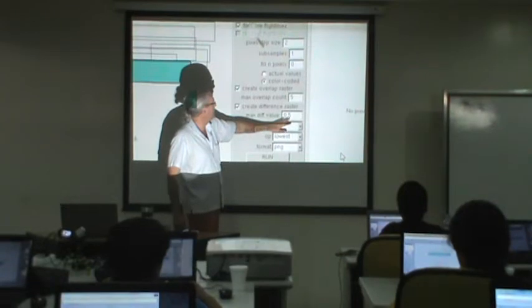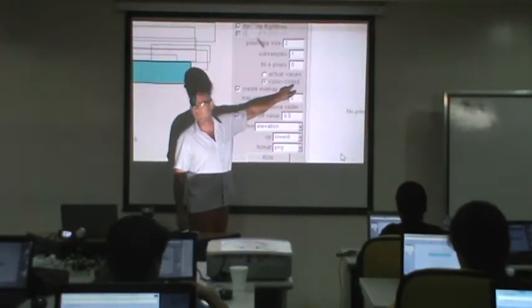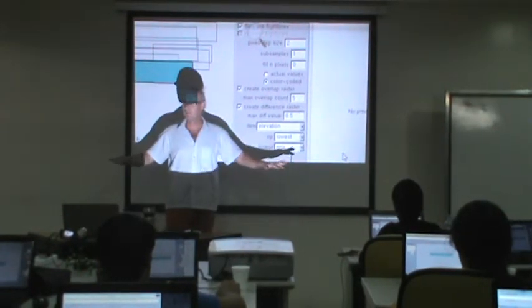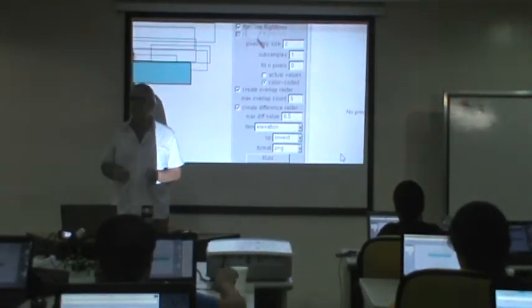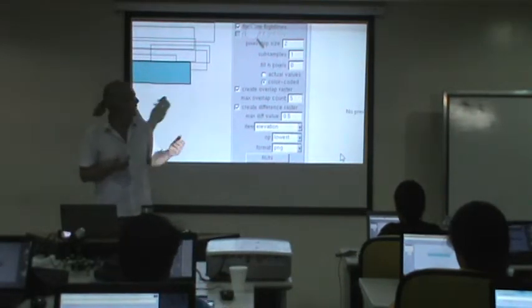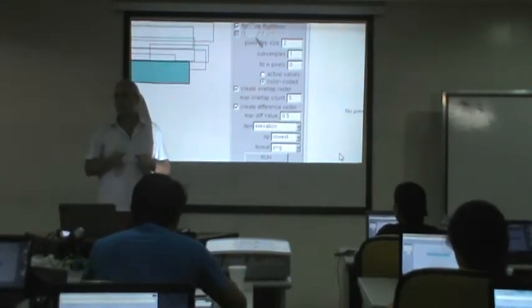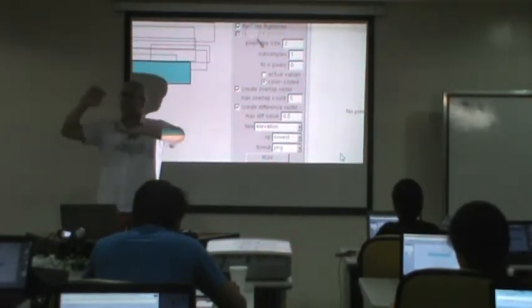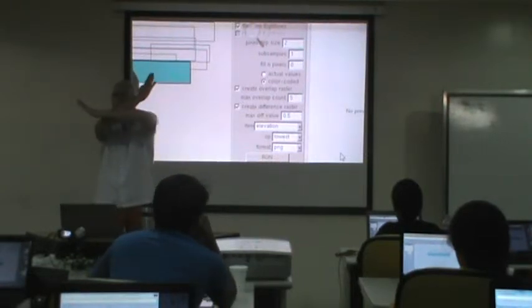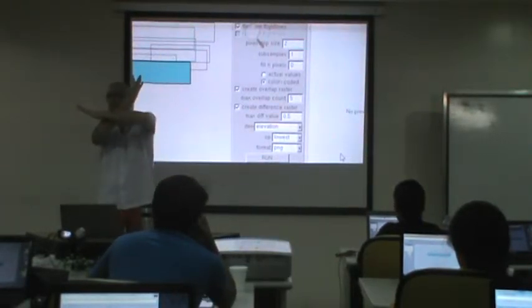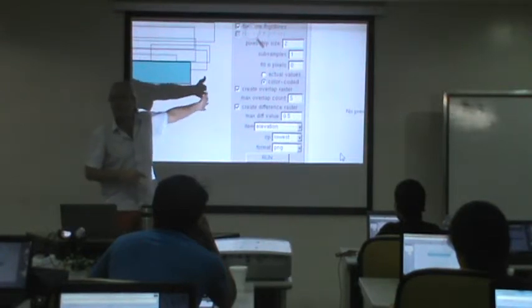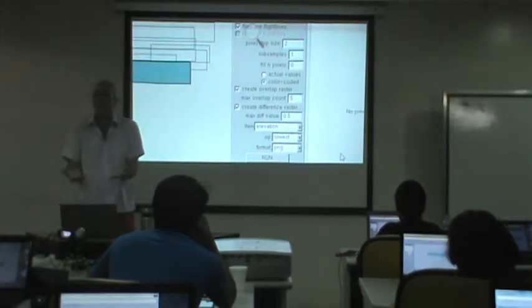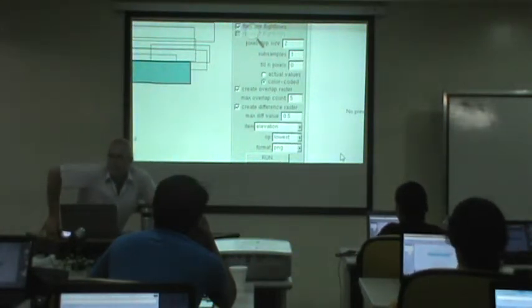Here, it may be useful sometimes to create the actual values and then afterwards create a histogram of the errors from the actual values rather than just a visualization. But for a quick quality check, this visualization is really useful because you have a bunch of flight lines and sometimes you have one flight line where the mathematics went wrong and the flight line is like this. Yeah? It's completely wrong. This will be very obvious in this visualization. You can pick it out right away. But if you just look at the LAS point clouds, it's, yeah.